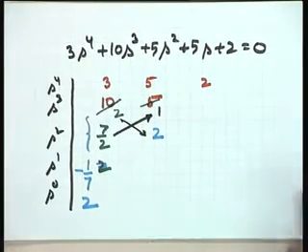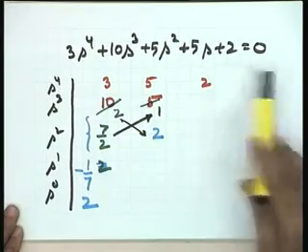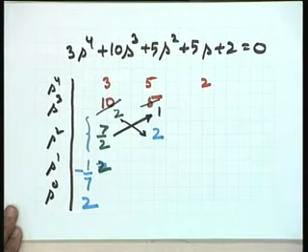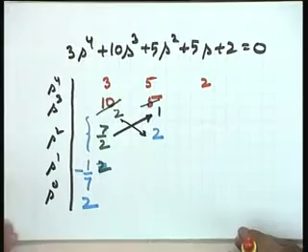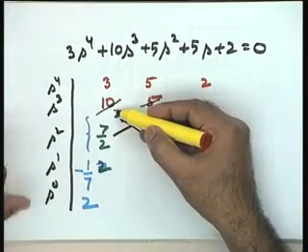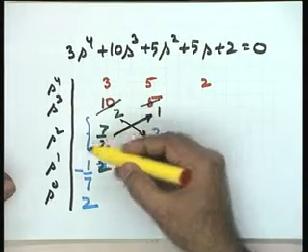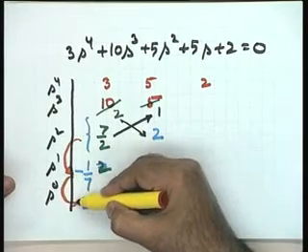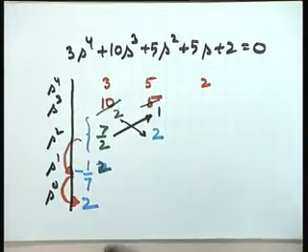Okay. So, looking at the first column, you can immediately say that the system whose characteristic equation is given over here is definitely an unstable system. How many roots are there in the right half plane? Please note the number of sign changes. So, positive to positive, no sign change, again positive to positive, no sign change, positive to negative, there is one sign change, and negative to positive, again a sign change. So, there are 2 sign changes and hence in this particular case there are two roots in the right half plane as per the Routh stability criterion. Okay?